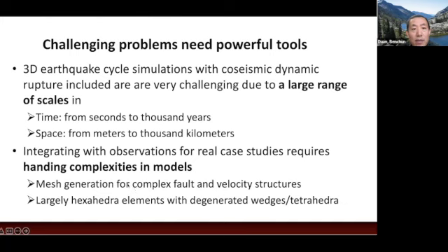Our code mainly uses unstructured mesh. We mainly use hexahedral elements, but if needed, we have degenerate wedge or tetrahedral elements to deal with complexity.